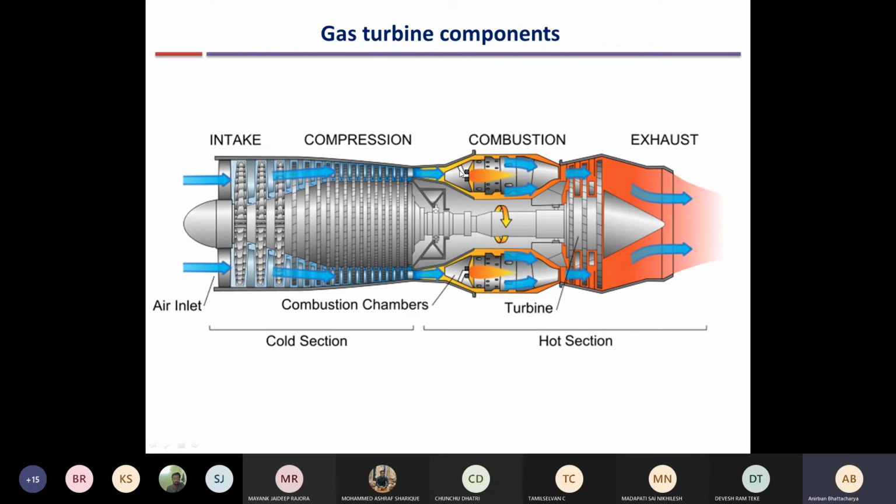So typically, the air fuel ratio in gas turbines is kept very high. It means the amount of air is kept very high as compared to the fuel. It is around 50:1, as compared to IC engines where it will be around say 15:1 or 18:1. So for hydrocarbons of this type, the stoichiometric ratio is around 15:1, or in that range.